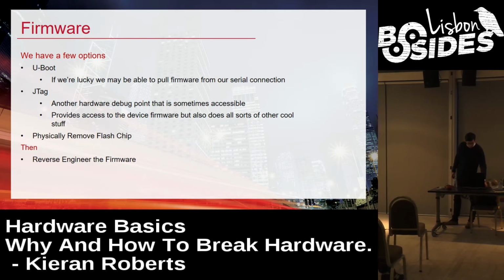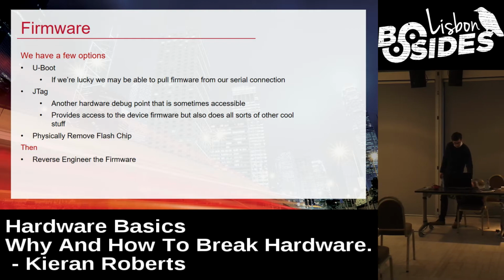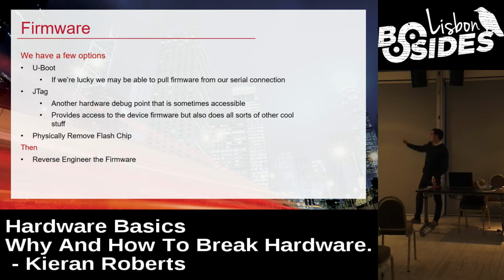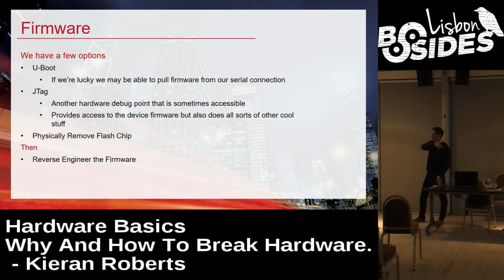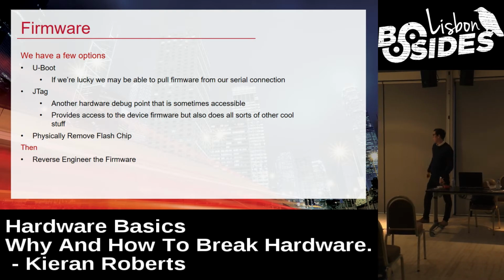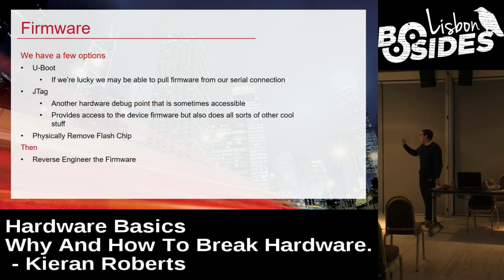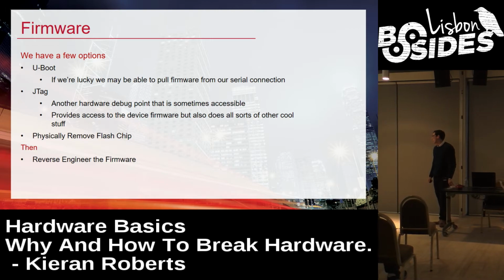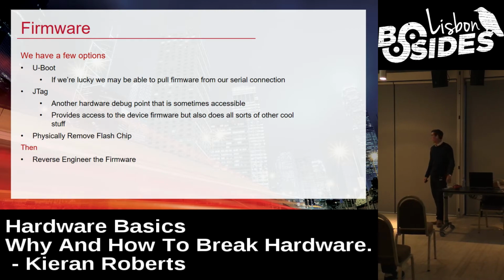U-boot is one potential way of getting access. That part where it was saying auto booting in 1 second, a lot of the time it's possible from there to boot into a U-boot console. There was a U-boot talk just before here. They probably discussed this way better than I do. If you hit the escape key, you potentially get dropped into U-boot or some other command. For this particular device, you have to type TPL because it's a TP-Link device. I think they had a glitching technique to skip that.